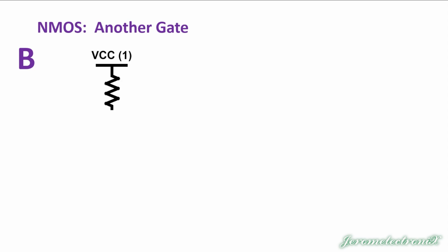I've got the VCC to start out with. Zigzag line, like on Charlie Brown's shirt, that is a resistor. That is a pull-up resistor because it is up high on the NMOS rather than down low on the PMOS. That is another transistor symbol. That is an NMOS transistor symbol. That will be input A. We got another NMOS transistor. That's going to be input B.